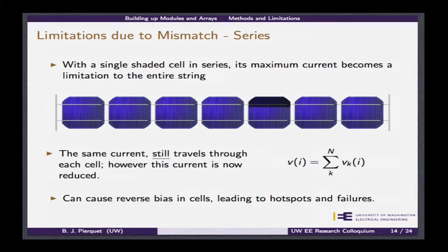There are other issues involved other than just the loss of power. If each one of these cells is putting out a substantially large voltage because it can't use all of its current, so its voltage goes up a little bit, and there happens to be a known voltage applied across there because you have some sort of power conversion circuit that's holding a voltage, this cell here can actually become reverse biased. So the total will ultimately mean that this may become a negative voltage.